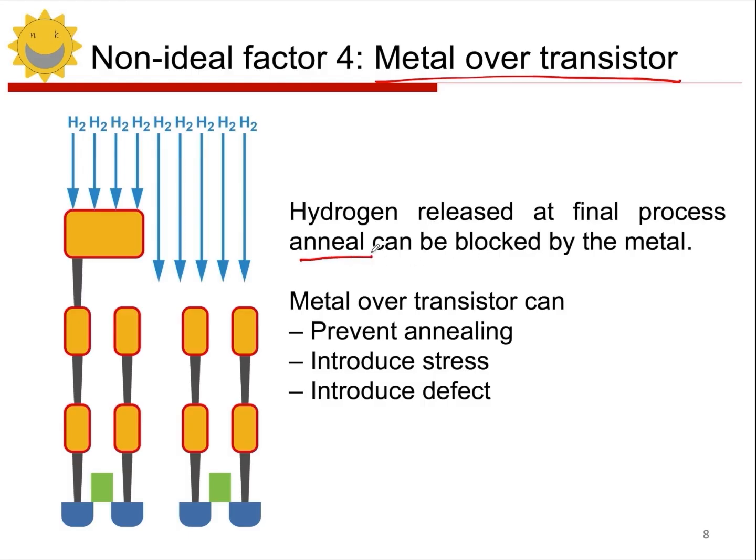Generally speaking, after processing integrated circuits, we need to complete the annealing step. What will happen during this annealing step? It will remove some oxygen atoms in the silicon, and it can also allow our doping, that is, the dopants and our normal silicon, to form such a perfect lattice structure. Annealing is required.